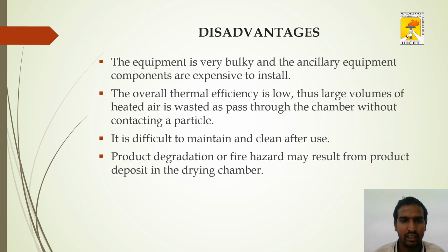And disadvantages: the cost of equipment is a major disadvantage, as the initial investment is higher. The overall thermal efficiency is low. Thus, large volumes of heat are wasted, passing through the chamber without contacting a particle. Because whenever spraying, sometimes only 40 to 50 percent of the air may contact the spray dried particles and the remaining 50 percent of the air gets wasted. Hence, from the energy consumption point of view, it is quite a big disadvantage.